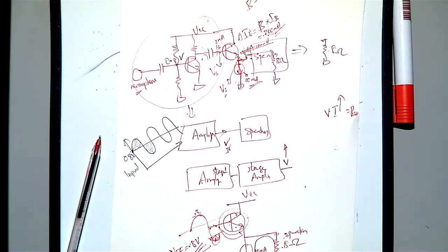So during the rising edge, what is happening is, this transistor, what is the voltage? Yeah, so during the rising edge, here you have got to say 0.8 volt. Then what is your VB? If you assume that V out equal to 0 first, then what is your VB? VB is equal to 0.8 volt, minus VE equal to 0, so 0.8 volt.